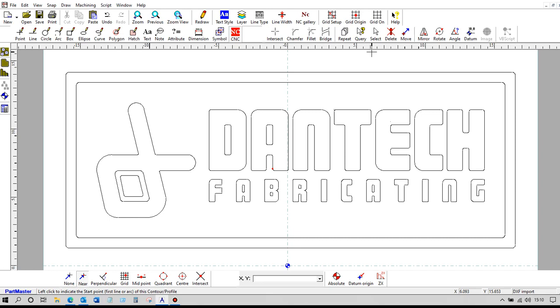In this video we'll show you how we can create the machining program for this nameplate. So I've started the CAD system and I've imported the DXF file. So what I need to do now is to create some contours. So if I use the NC button here and then choose the outside shape.